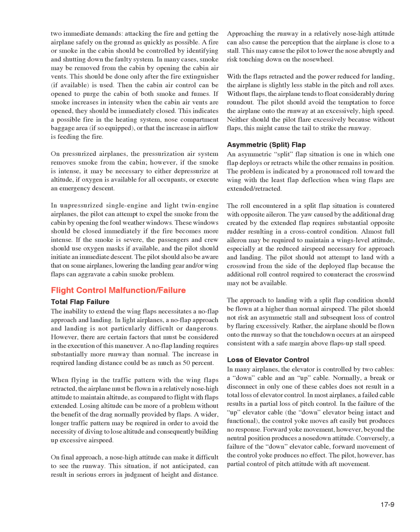The inability to extend the wing flaps necessitates a no-flap approach and landing. In light airplanes, a no-flap approach and landing is not particularly difficult or dangerous. However, there are certain factors that must be considered in the execution of this maneuver. A no-flap landing requires substantially more runway than normal. The increase in required landing distance could be as much as 50%.